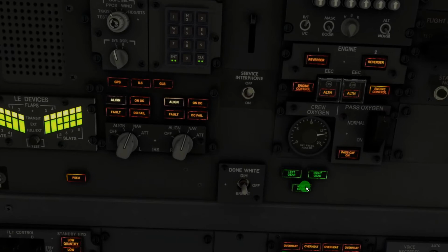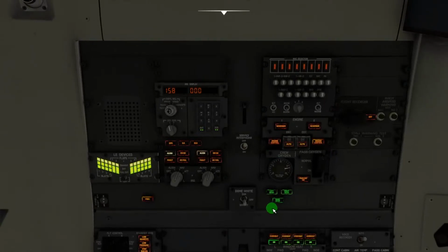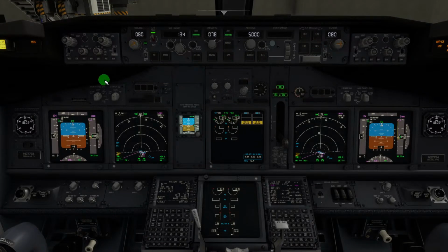Maybe you can have a light failure or any other problem. So if you have the 3 greens here or the 3 greens here, you will have all your gears down and locked. Or 2 here and 1 down, it doesn't matter. Once 1 green light is up, it means that you have the respective gear down.